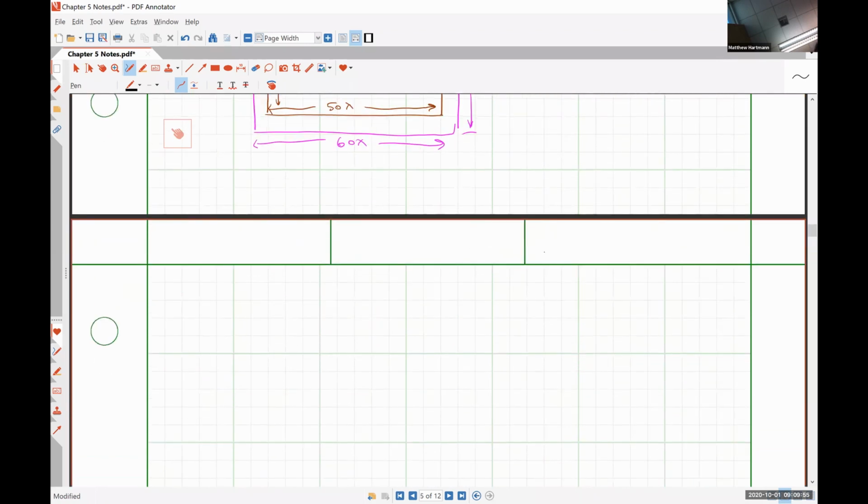I guess we'll have to go down here. The capacitance of our poly to poly 2 capacitor is going to be Cox prime times 20 lambda times 50 lambda, which is 950 times 10 to the minus 18 farads per micron squared. 20 times 50 is 1,000, and then I'm going to have 0.3 microns squared, and this gives me a value of, let's see,